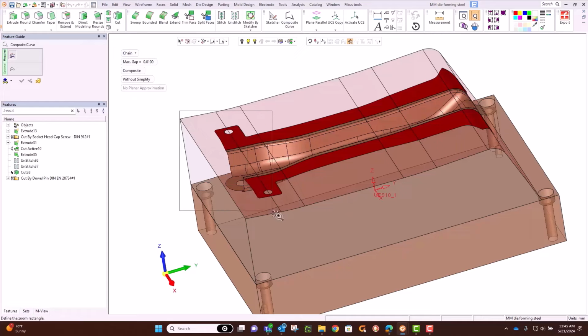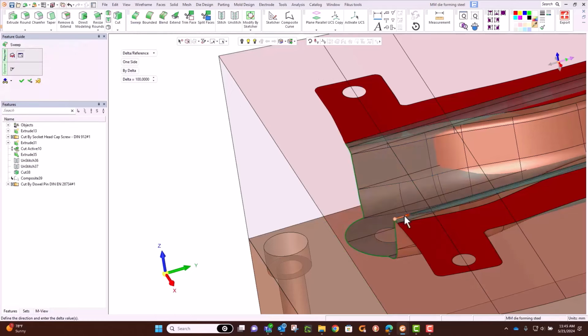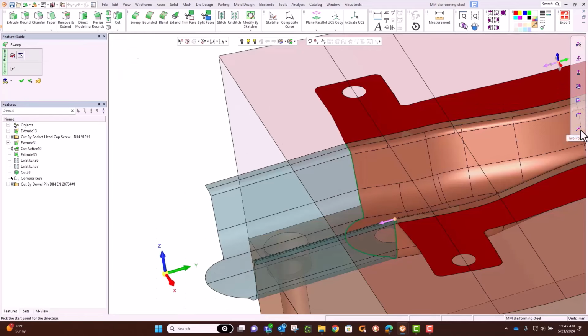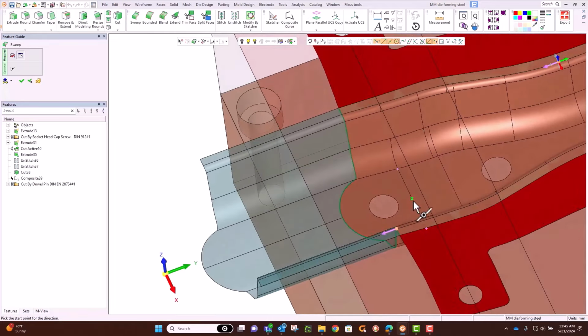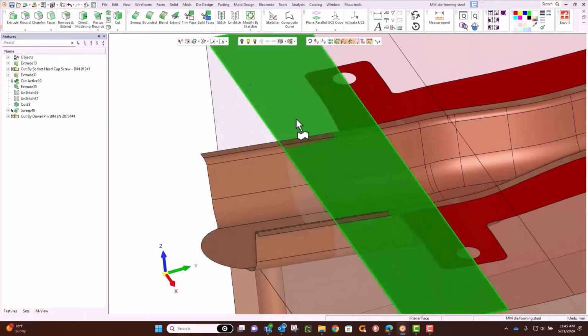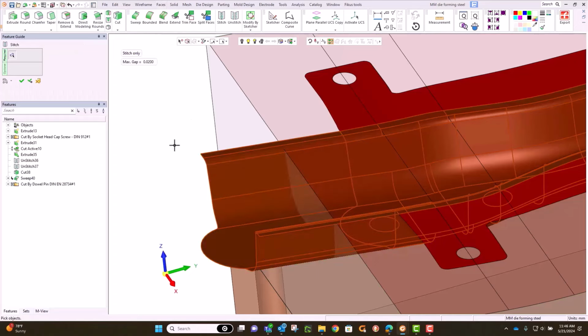In this case, I'm going to grab the open end of my part. I know I need to extend those faces off to the end here. So I'm just doing a simple sweep of a few faces, chaining it along that edge, setting a direction now where I work right through this face. So it comes off of that face clean. Each of these could be tangent, or in this case, I know the bottom and top are. We'll stitch those two together. Again, an incomplete solid that I have that I'm going to work with.